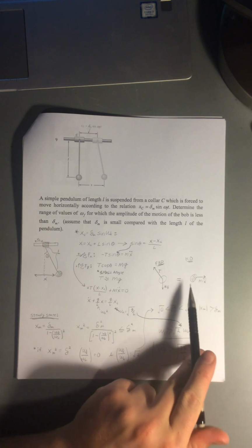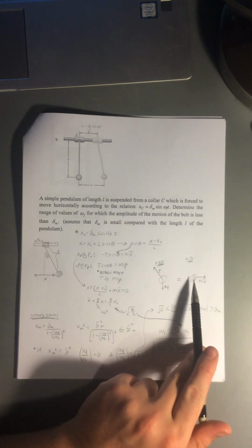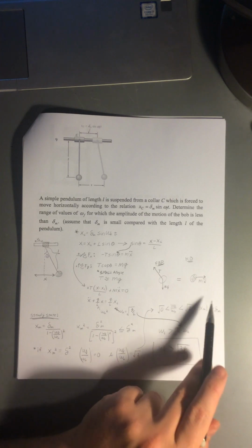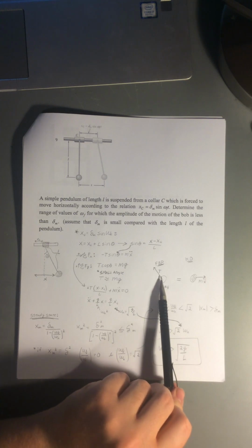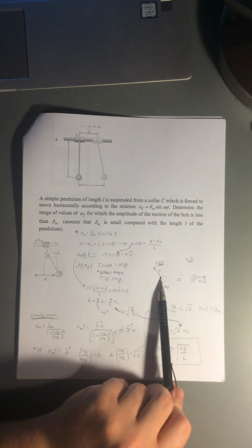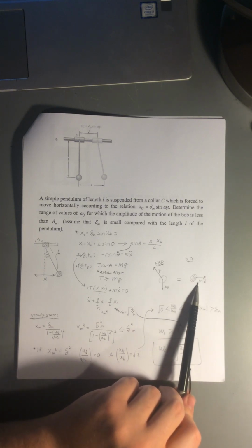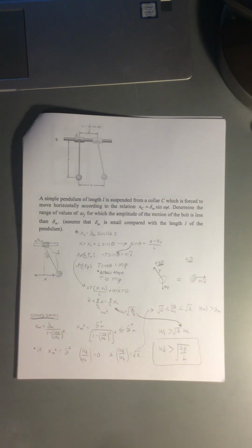And that has to equal our mass times acceleration going to the right, and we know that our acceleration is also equal to x double dot, so I've replaced that. Doing these two equations here, summing the forces in the x and y directions, gives us these two equations. Looking at the free body diagram and the kinetic diagram, we can tell that in the x direction we have the portion going to the left, which would be negative T sine of theta, and that has to equal this mass times acceleration in the kinetic diagram.